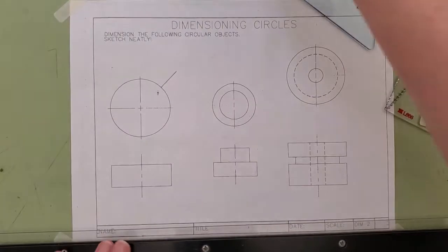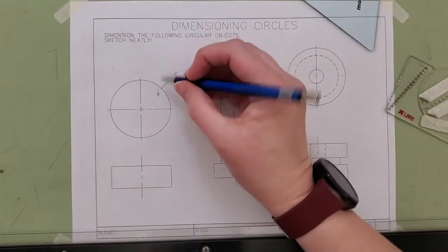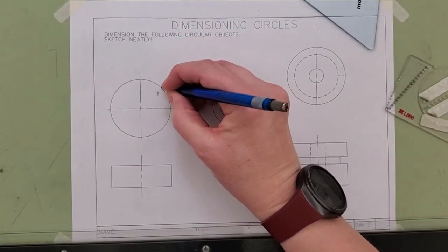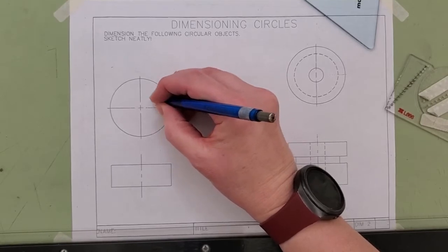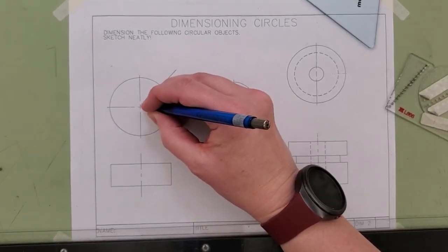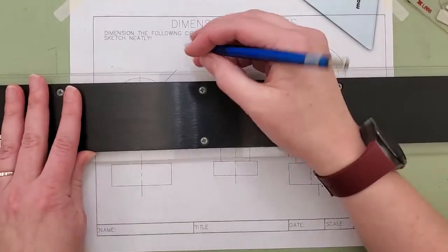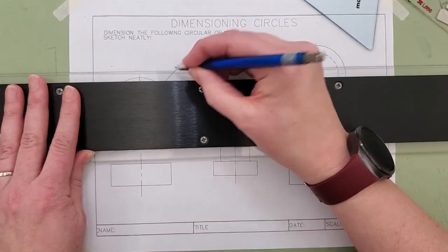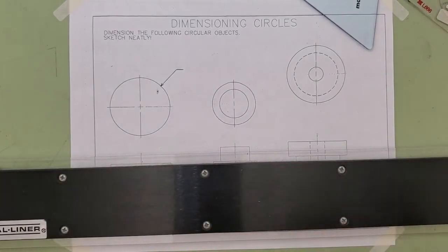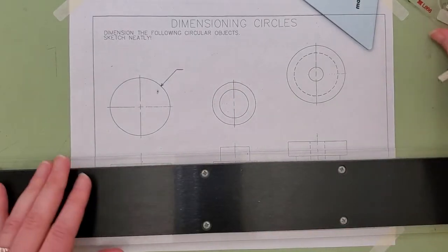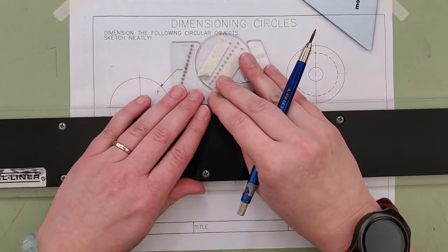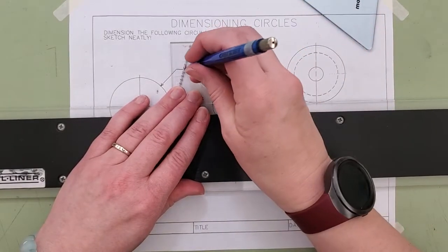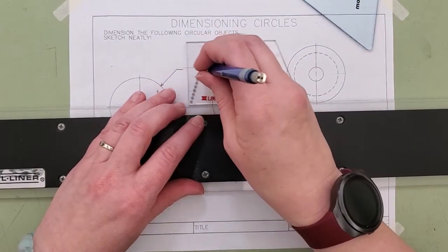you are going to draw a line up with the arrow touching the circle, but if I continued that line down, it would go through the center point. Okay, it would then level out, okay, with a horizontal line. Okay, and finally, we would use our lettering guide. When we're going to actually do dimensioning, you need to use your lettering guide, and I still go with the